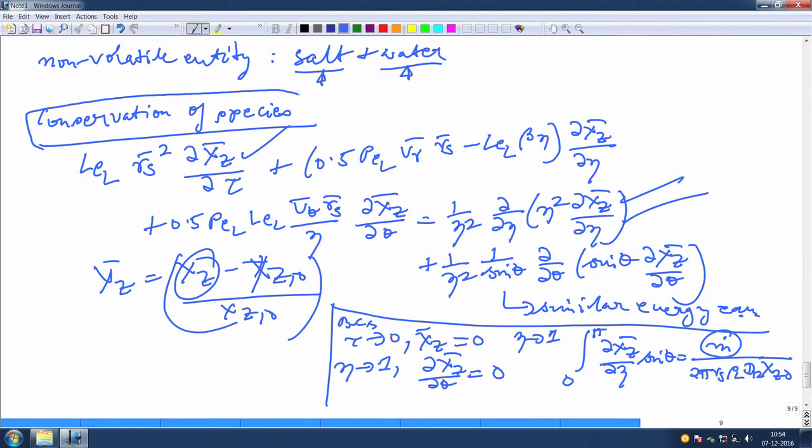In addition to this, you can solve this mass transfer. So, this is the conservation of species. For 2 species you can write this. For N number of species you have to write it for the other species components also, and you have to know the diffusion of one species into another. So, it becomes a multi component diffusion problem, which is similar to what happens in a multi component fuel droplet. Say for example, you have a kerosene droplet which has got dodecane, N-hexane, N-pentene,